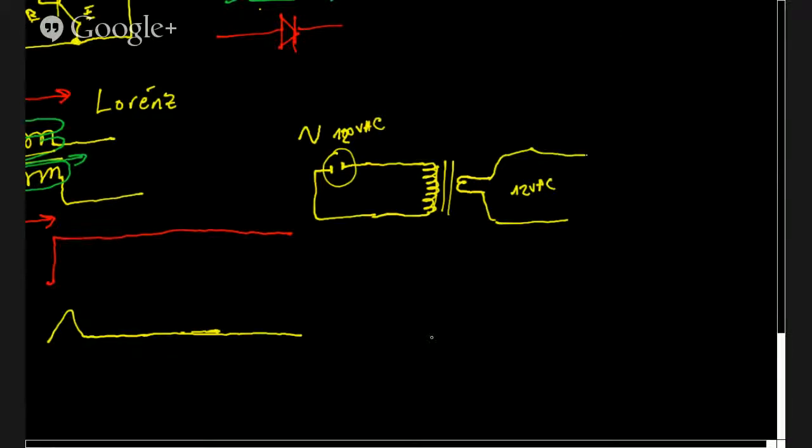We'll feed that into a rectifier, which is our diodes, because diodes only allow current to flow in one direction. Actually, we'll do this first. If we were to put a diode across here and looked at the waveform, instead of our positive and negative cycle, the diode would end up with just the positive cycle, and the next positive cycle, and the next.